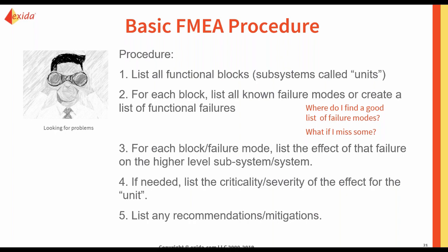I see people putting together a spreadsheet and trying to do an FMEA, and they don't even list half the failure modes. And what happens if you miss one? You're going to miss a potential error or omission in the design. You've got to have a good list. If you have things that are pretty bad, and we have to do something about it, I need a mitigation technique. Well, are you thinking of the best mitigation techniques? Obviously, the best are things that can be implemented with the least amount of work and are most effective in actually mitigating the potential failure effect.